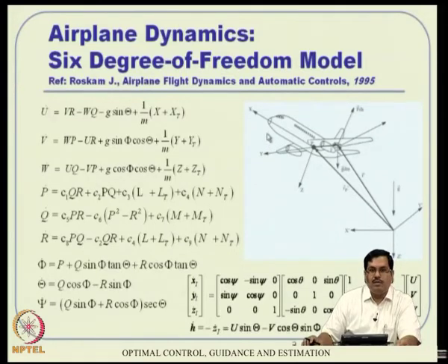Then anything that is generated from flight test essentially falls in the bracket of what is called parameter identification, because that is where you want to identify how these forces and moments actually act on the vehicle. Roughly speaking, the aerodynamic interaction of this vehicle is not very well understood from a physics point of view. That is why we need several rounds of experimental study, combined with a deterministic model, to get a fairly accurate model.